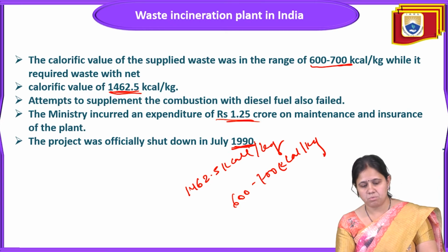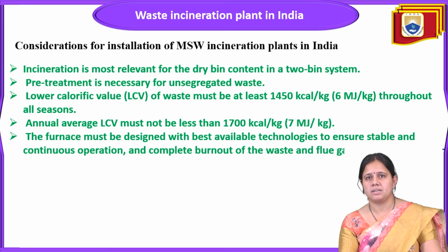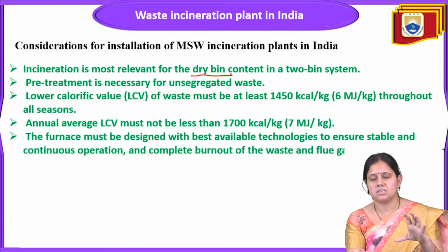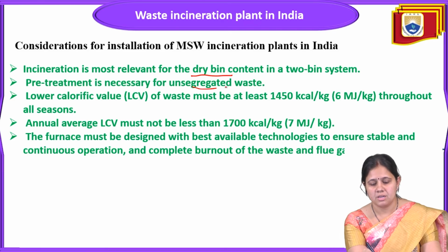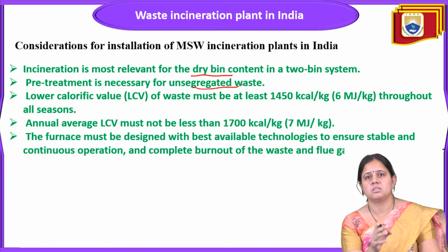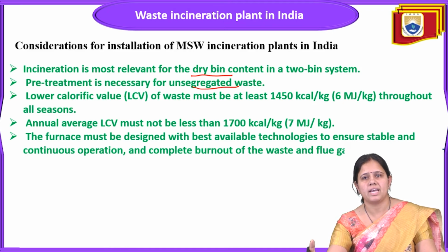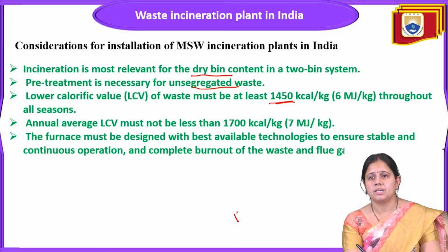So what are the important considerations for the installation of an MSW incinerator plant in India? Incineration is most relevant for dry waste, so dry bins are important, which means a two-bin system. Pre-treatment is necessary for unsegregated waste. A pre-treatment unit is a must because our waste is unsegregated, and the lower calorific value of the waste must be at least 1415 kilocalorie.